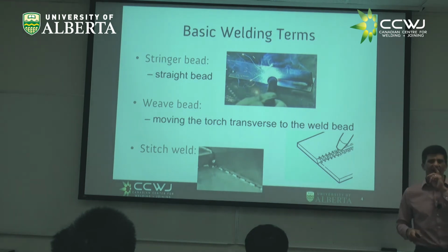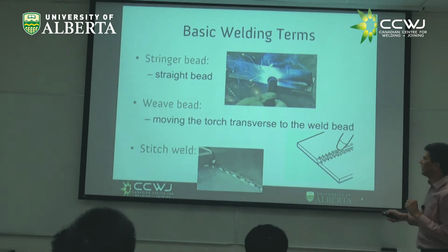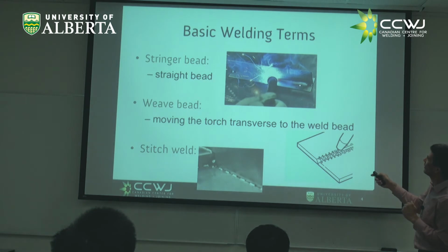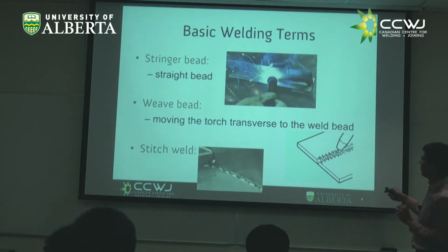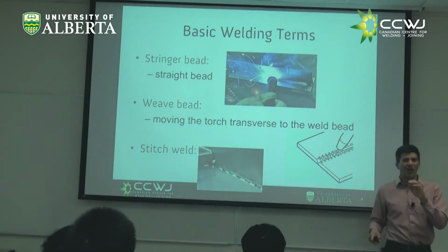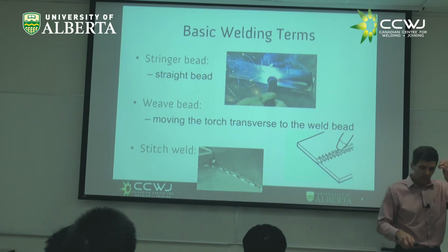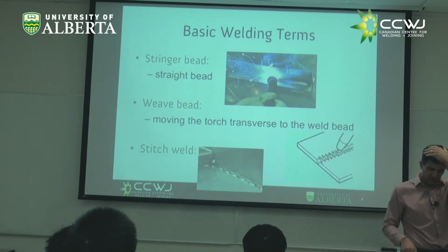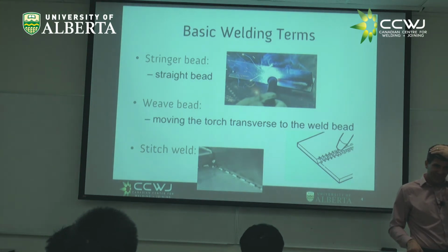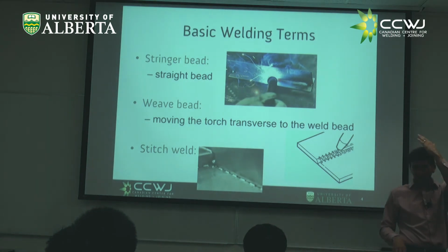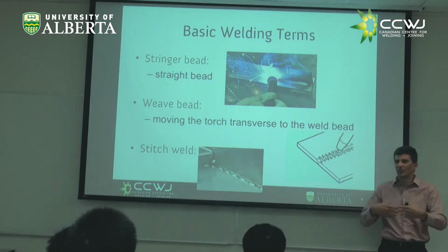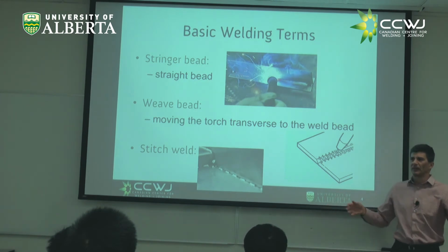Now, a question to you. In which weld do you think we're putting more heat, in a stringer bead or in a weaving bead? Of course, right? Because I'm moving relatively slow. Now, if I'm putting more heat, do you think it's going to cool faster or slower? If I have more heat, it's going to cool slower, right? Because I need more time to dissipate all the heat I put, right?